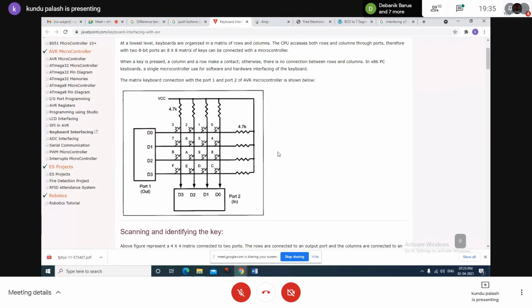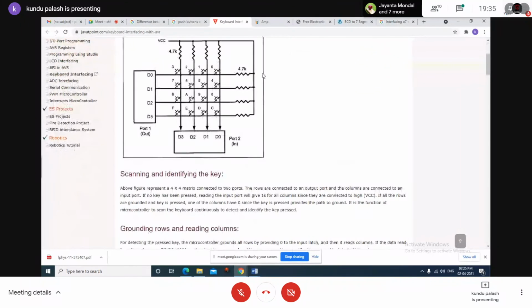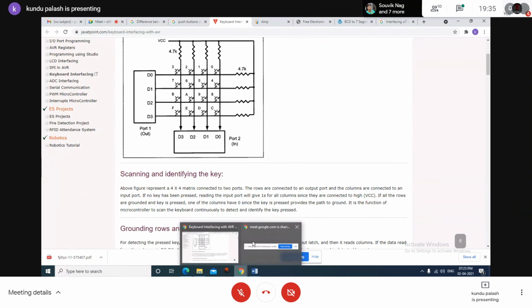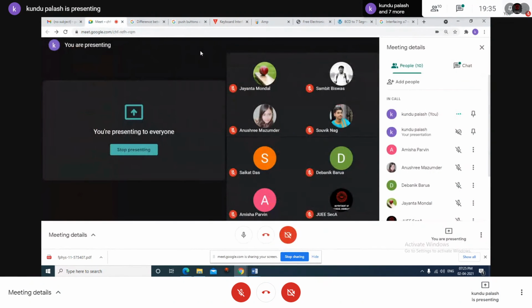So I will discuss what is the algorithm for the key sensing logic. That is a typical example of how the matrix keypad can be interfaced via an 8255 port to the 8085 microprocessor. The only thing you have to understand is the logic behind this, how to read the code from the pressed key, and for that purpose the 8255 PPI is required.